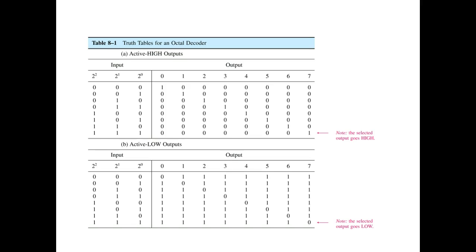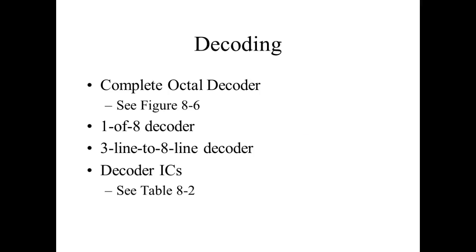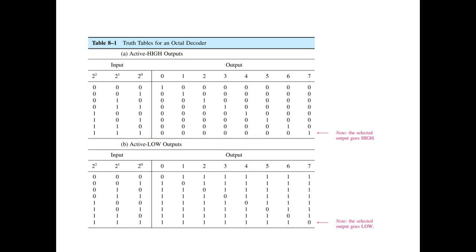Yeah, and I said that several times. If you look at a chip and you look at the pins and it says A, B, C, that is weighted binary. A is the least significant bit, and how far it goes up to is the most significant bit. So a 74138 is going to be A, B, C because it's a 3 to 8 decoder.